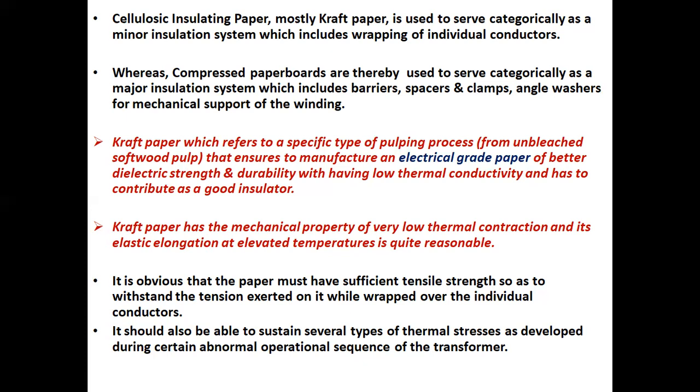It is obvious that the paper must have sufficient tensile strength to withstand the tension exerted on it while wrapped over the individual conductors. It should also be able to sustain several types of thermal stresses developed during certain abnormal operational sequences of the particular transformer.